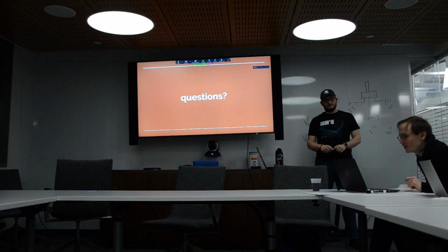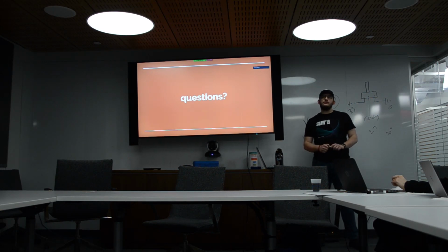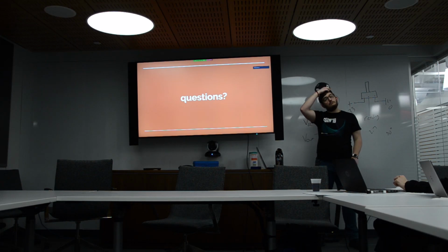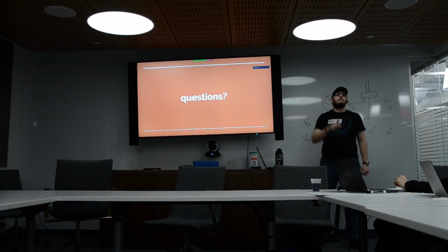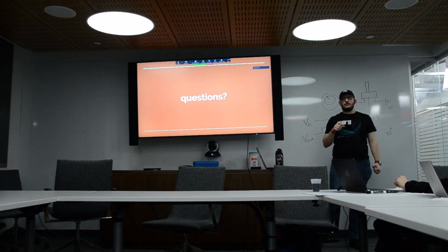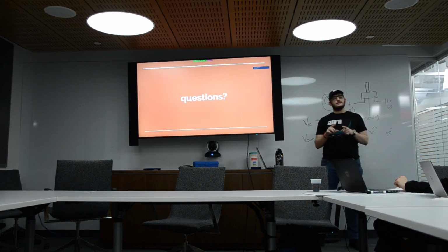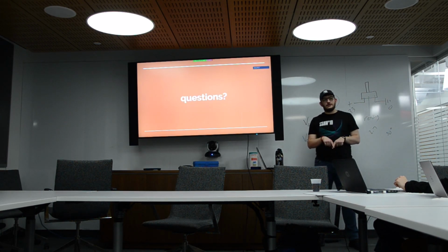Someone was curious about a heat gun. Is that a good piece of equipment? Yes and no. Heat guns are useful for desoldering things and for getting them back on, but they are not the best option for getting chips off. They're good because you can spend $20 on one and get things that work passively, but unfortunately that also means that you tend to melt the entirety of the board around the heat gun.